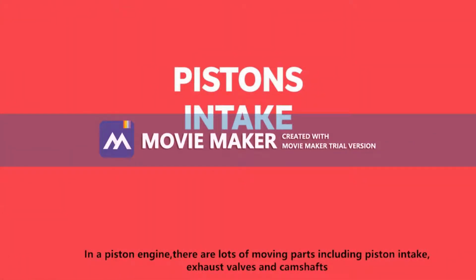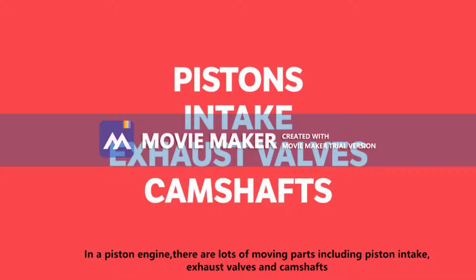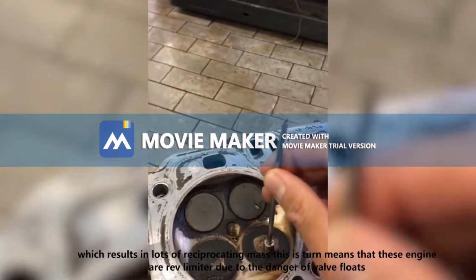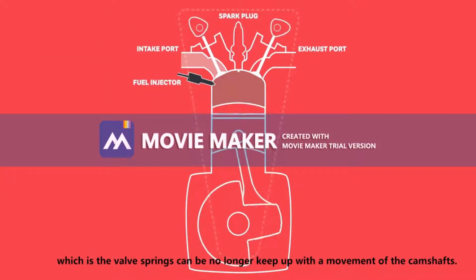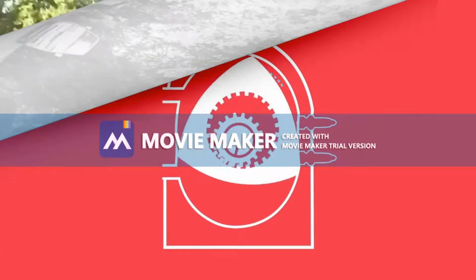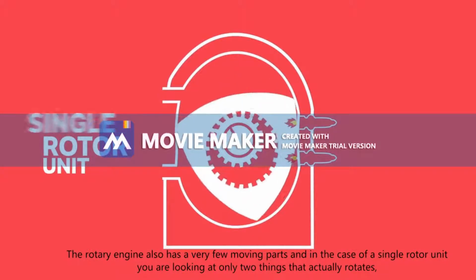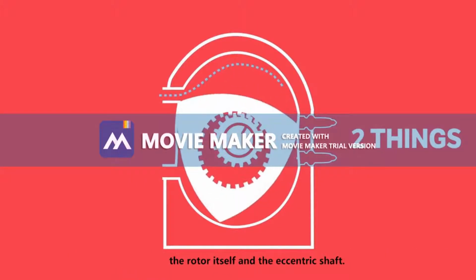In a piston engine, there are lots of moving parts, including pistons, intake and exhaust valves, and camshaft, which results in lots of reciprocating mass. This in turn means that these engines are rev limited due to the danger of valve float, which is when the valve springs can no longer keep up with the movement of the camshaft. The rotary also has very few moving parts, and in the case of a single rotor unit, you are looking at only 2 things that actually rotate: the rotor itself and the eccentric shaft.